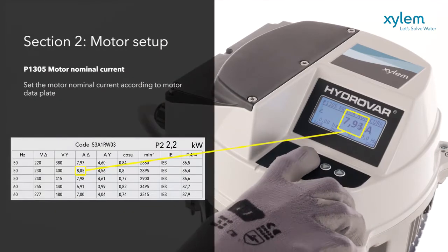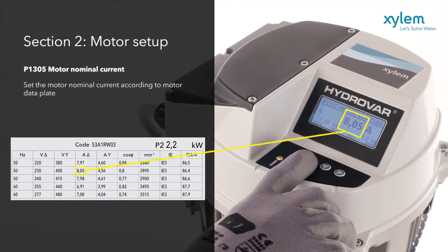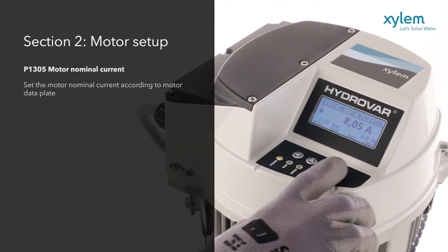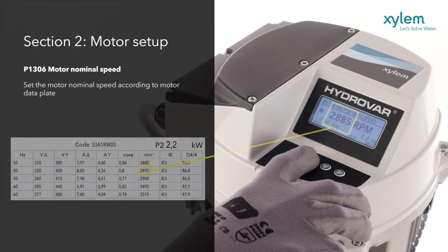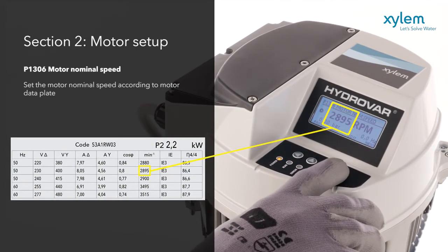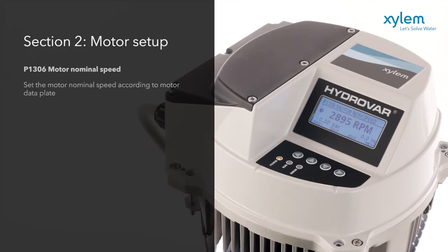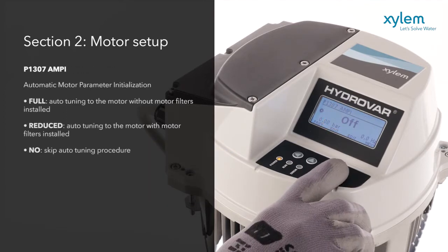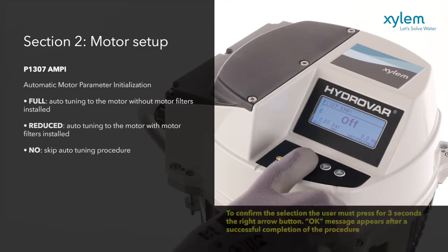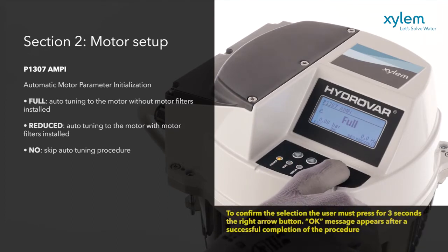If a generic motor is selected, the nominal current and nominal speed of the motor has to be set. Note that the Automatic Motor Parameter Identification process, AMPI, can take up to 3 minutes, during which time no other actions are possible.